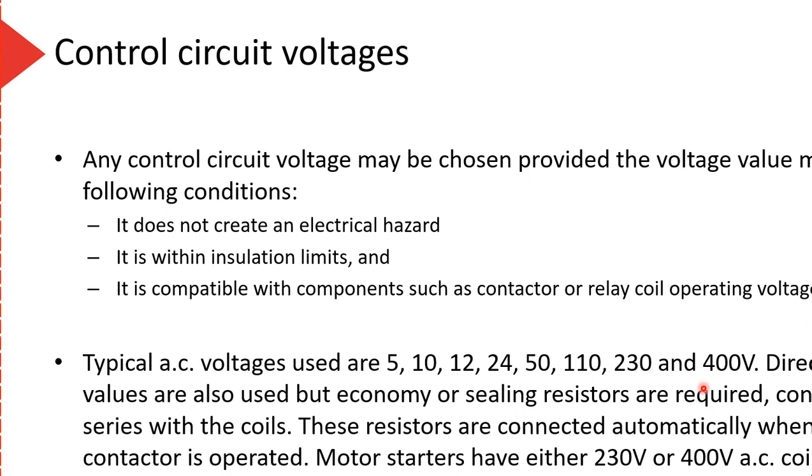That's real nice, right? If we think about, again, that example of the emergency stop circuit in 402, I could make all the controls on that 12 volts and then have a 12 volt coil switching my contactor, which is switching the 230 volt sockets, but it doesn't have to be 230 volts on that coil. That means that all those start and stop buttons, well, mainly the stop buttons at the desks, could all be 12 volts if I wanted them to. So if I'm in there with a class full of students and they're gumbies like they are, and they want to get in there and play with stuff and lick the wires, then they're not going to die because it's only 12 volts. Yeah, that's nice, right?